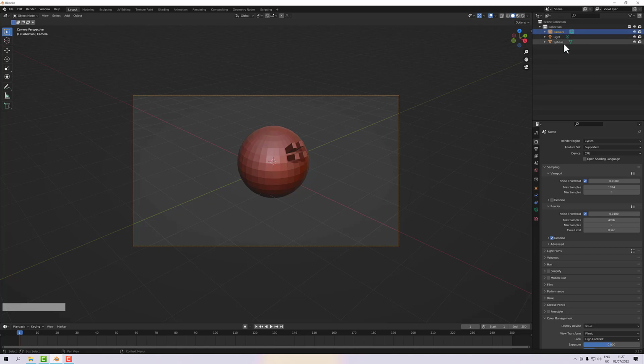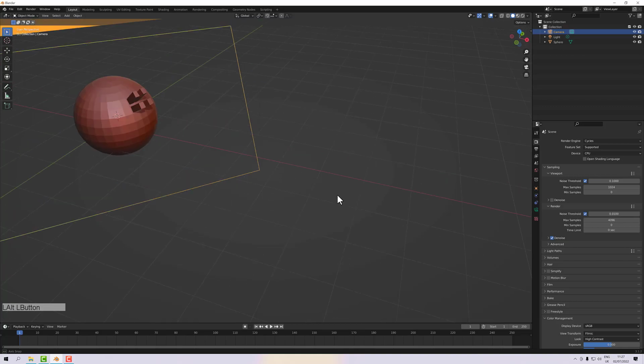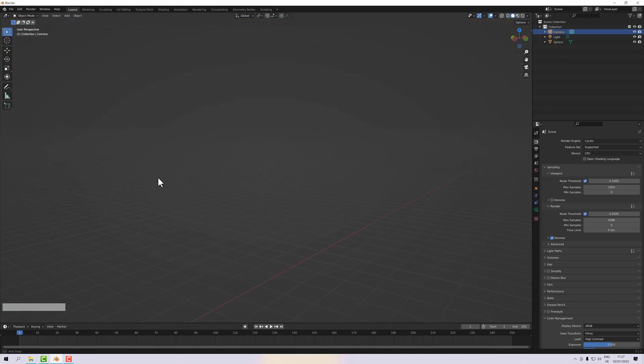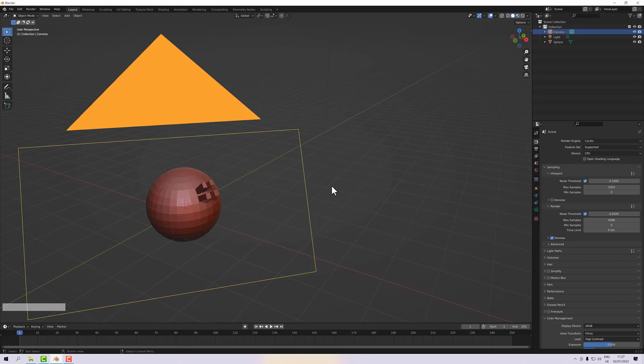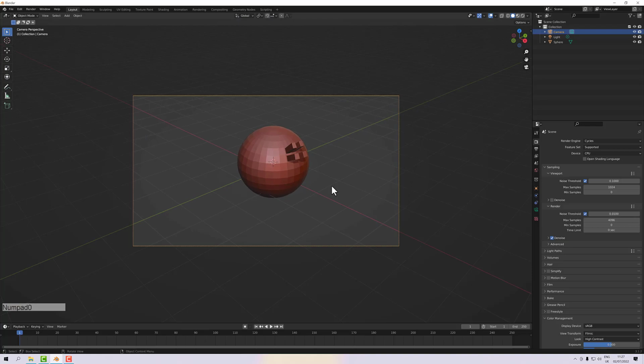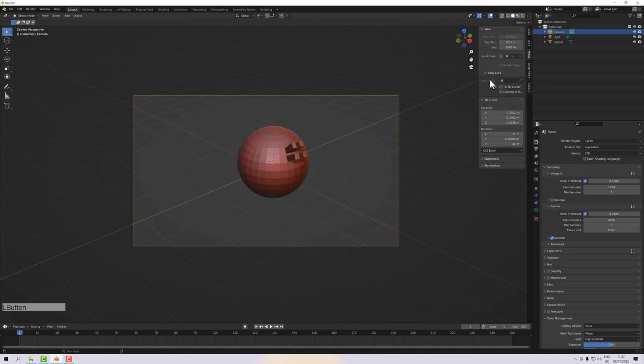It's just for your modeling options. So if I currently press Alt to try and rotate that round, it doesn't work. It just switches me back to the view camera. And if I press the 0 key again, you'll see it's not changed. But over here, if we press the N key, we get our little pop out here and go on to View, and about halfway down the list there's Camera to View. So that's locking the camera to the view.